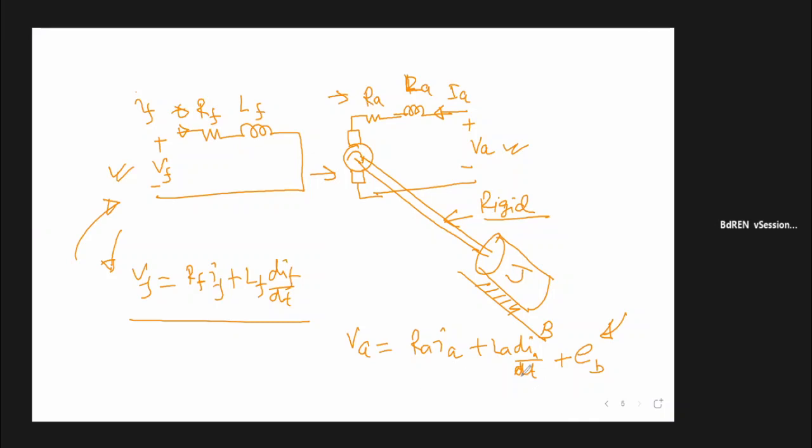Then if we write the equation in this way, in a DC motor, if only the resistance is controlling the armature current, then thousands of amperes of armature current will be flowing through your armature, and in the wink of an eye, your armature will be getting burned. For this reason, at the starting point, we need a device to start the motor that is called a starter. Have you seen it in your laboratory?